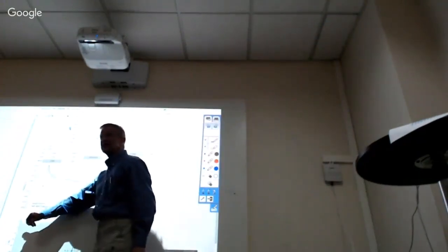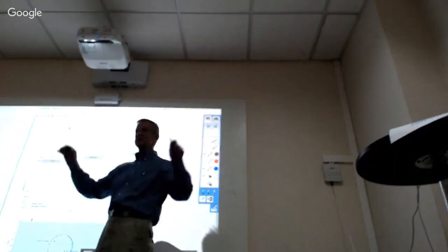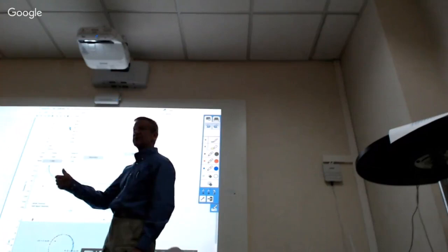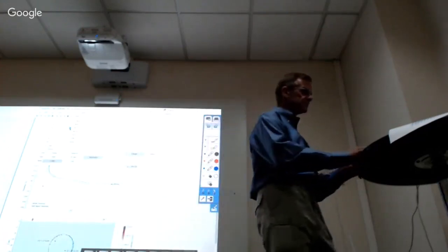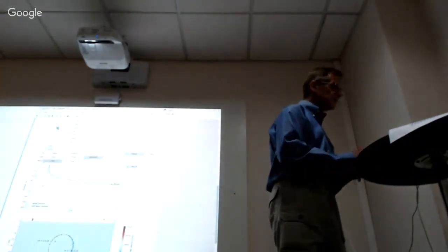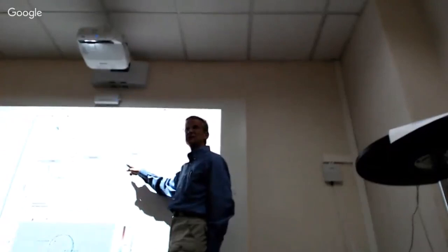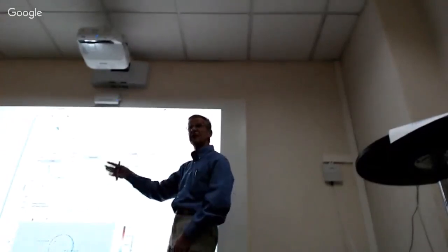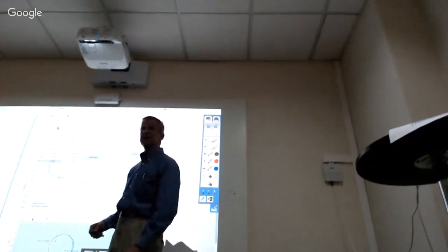We talked about exciting the object. Okay, so that's done. That builds up the charges. That's the first part. Second part is measuring. When I'm sitting up over here, if the M electrode is sitting up over here, my apparent resistivity is 1,100 ohm meters, which is all kind of consistent with this being a resistive body, right?